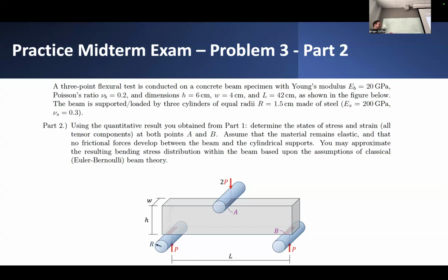So you're right. Indeed, if we have this vertical pressure, it should be balanced. And really what this means is, anytime you have one of these blocks of stress, if I'm trying to determine different components of stress acting in different directions, I can use the fact that the stress acting on the top of this block is P0, the contact pressure, which has to be equal to sigma YY.